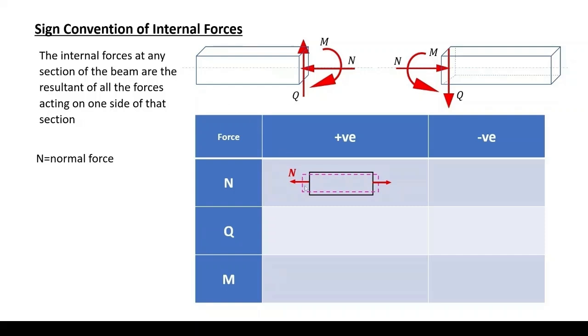And we recall that the normal is in the direction of the center line. Our element under compression normal force, the deformed shape. Therefore, an element under tension normal force has a positive force. Compression normal forces are negative forces.